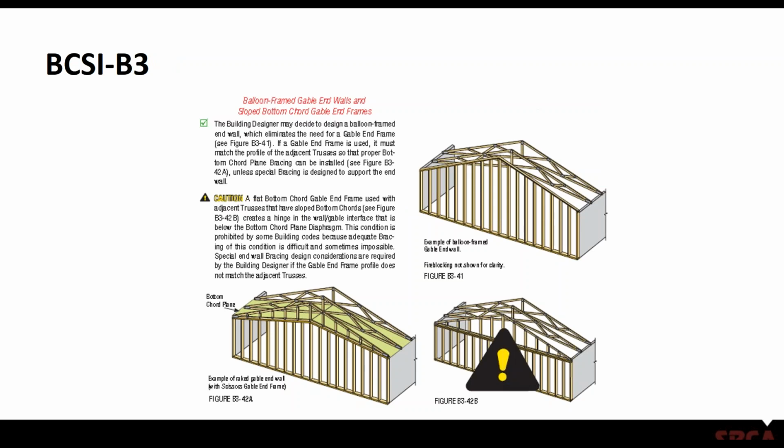In BCSI B3, they provide a caution that it's not recommended to do that. If you're going to have that situation, the top of the wall needs to be at the same elevation as your ceiling diaphragm, unless some type of special bracing is called out.